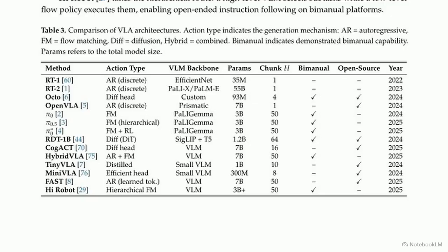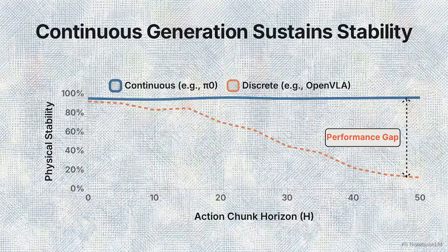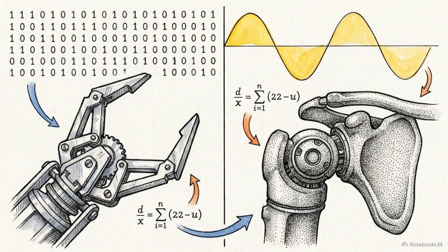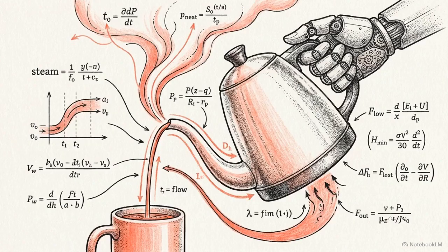We can track how these mathematical differences translate to hardware by looking at standardized simulation benchmarks. This table compares success rates across standard evaluation suites. On the Libero long tasks requiring complex navigation, the flow-based Pi0 scores 78.4, while the autoregressive OpenVLA reaches just 53.7. This performance gap suggests that coherent, continuous generation is a significant factor for long-horizon physical stability. Some researchers have moved toward hybrid architectures, which route binary gripper commands to an autoregressive head and smooth joint motions to a flow-based head. While the field continues to evolve, the current data shows flow-matching architectures setting the high watermark for tasks requiring stable, continuous interaction.